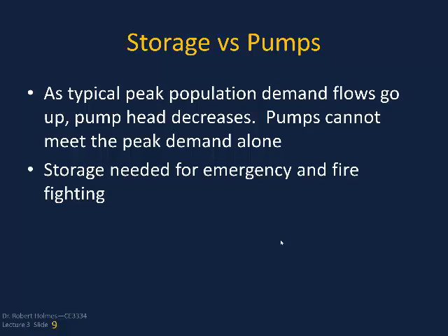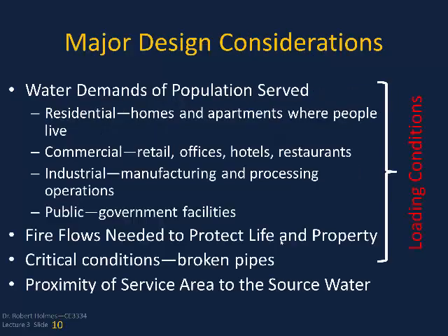But if you've got water in storage in these elevated storage tanks and water towers, then you essentially have a little bit of factor of safety built in there. And with the storage, you also don't have to pump as much water during peak demands, such as emergency firefighting or peak demand during the particular time of day.